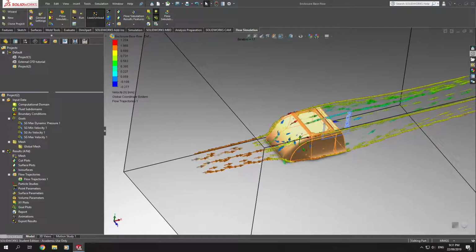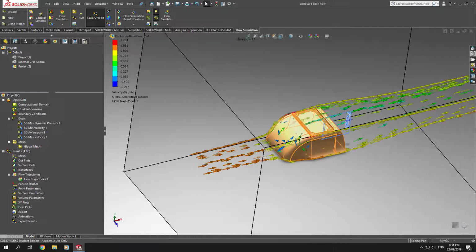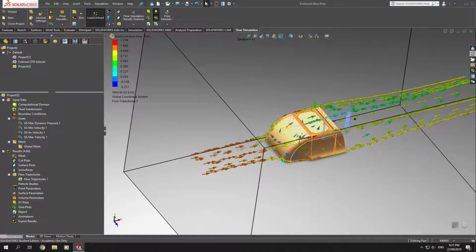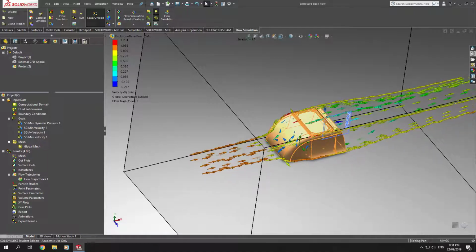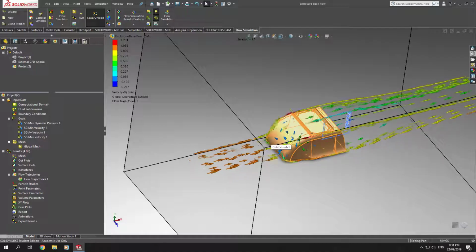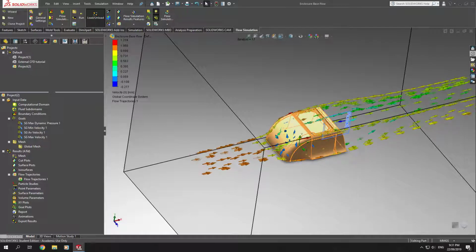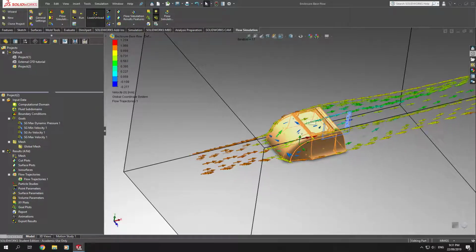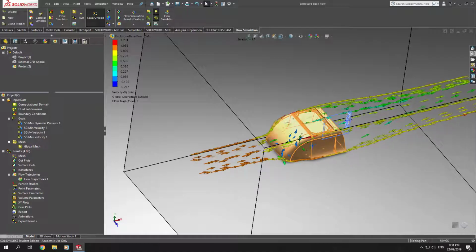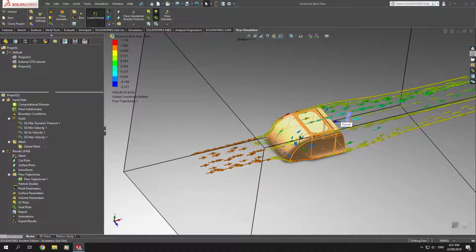Basically, what you're seeing is the flow of water hitting this model, and as you can see, it's orange, which means it's going at quite a fast velocity, and it's slowing down, which means it's having some drag, the blue arrows. And you can see on the sides it's actually speeding up, which means it's increasing in velocity, which means it's got quite a nice shape to it. It's quite optimized well, and it's slowing down because at the end it's gonna cause some turbulence and drag.